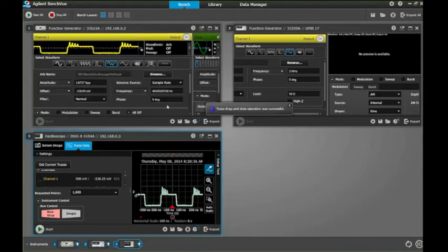What I want to change here is the voltage, back to 1 volt peak to peak, because that's what my original signal was. And since my requested number of points is 1,000 points and my total time scale is about 1 microsecond, that means that my sampling rate is 1 nanosecond per point, or 1 gigasample per second. So do that, and let's go back to the scope and see if that worked.